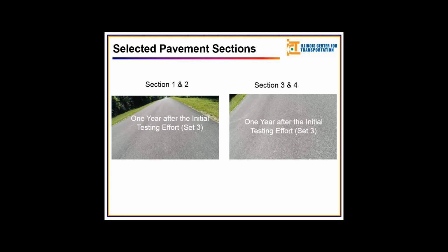One quick comment, actually. This project is intending for local agencies to actually start to use what has been established for mainline highways for many, many years. Every state DOT has an FWD device. Every state is using FWD testing as structural condition assessment. However, when you look at local roads, which are really not getting so much attention paid, they never actually end up doing this, local agencies.